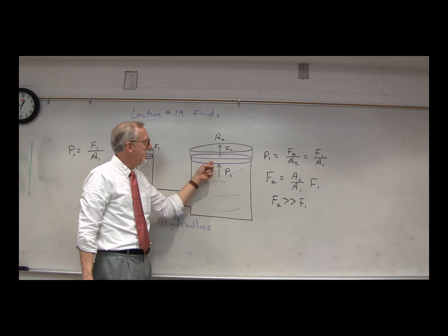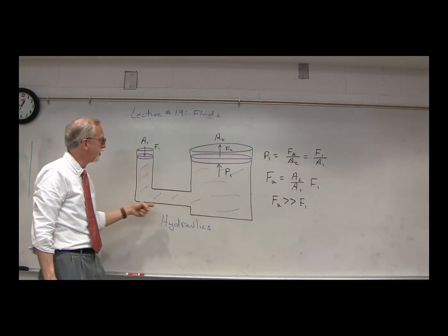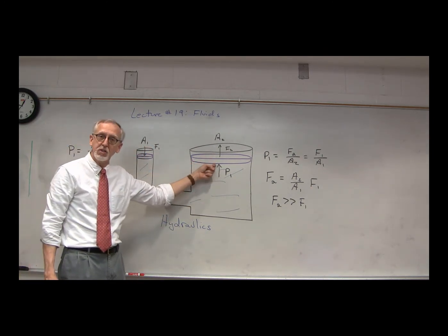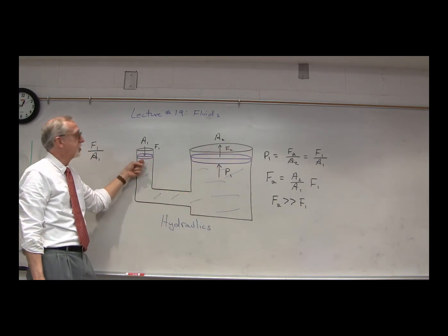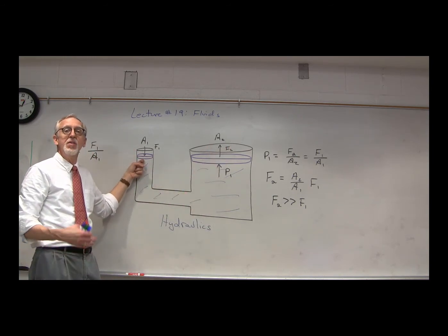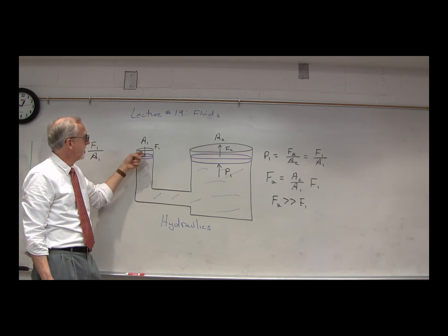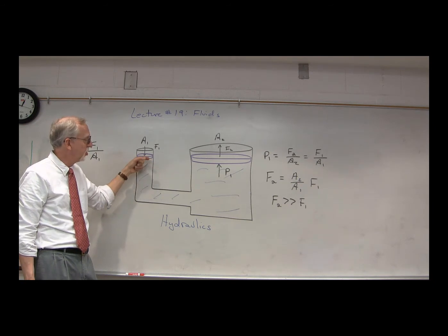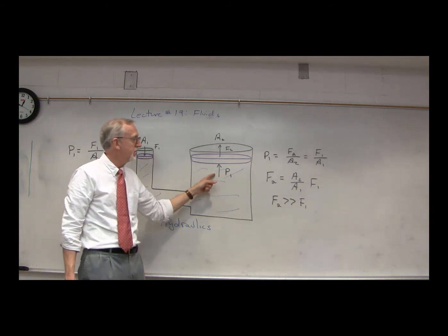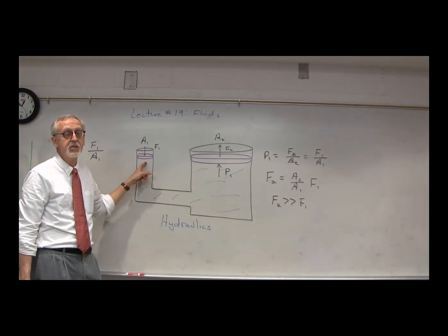But you do not need to apply a force on the fluid that's equal to the force being exerted by the piston pushing the car up. You can exert a much smaller force with a hydraulic pump, applying a smaller force as long as the area of the tube over here is much smaller than this tube. You can exert a much, much smaller force.